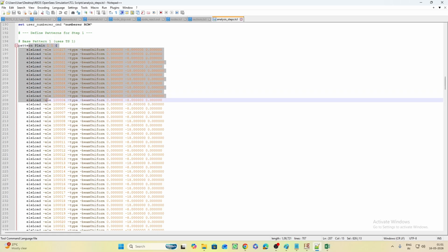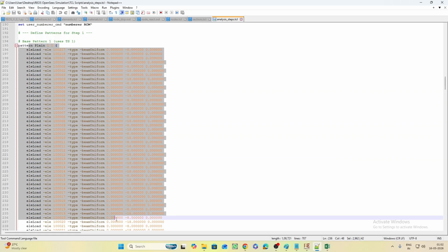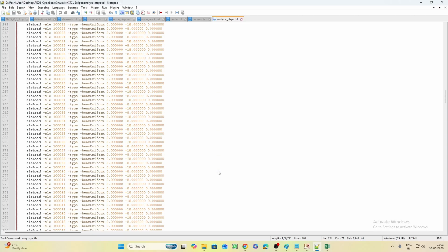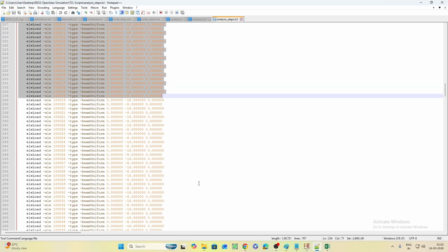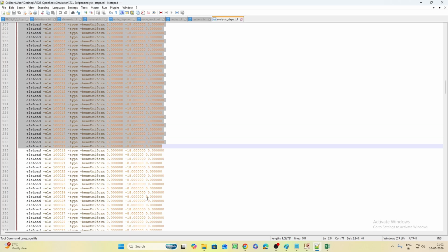And this is the load application. We have two kinds of load, the live load at the floor level and the infill overloads, but OpenSees will not use those commands. It has its dedicated command for element loads. The same will be used. So by looking at this, you will not understand whether it is live load or some other loads because they will follow the same command.